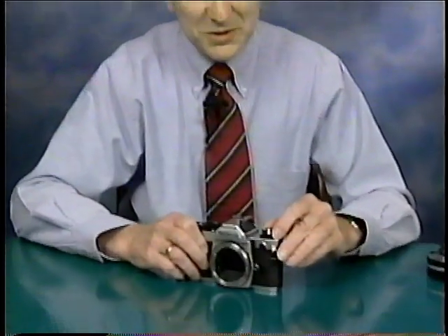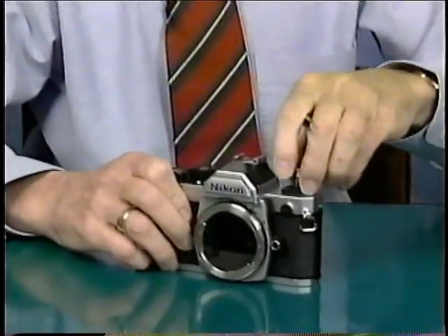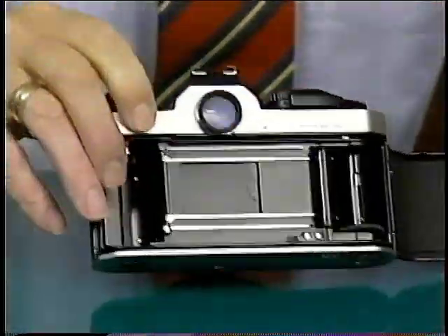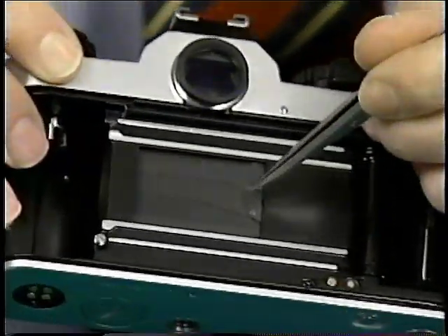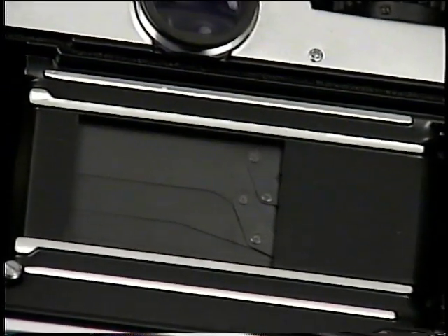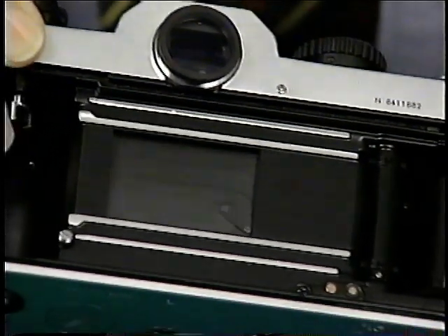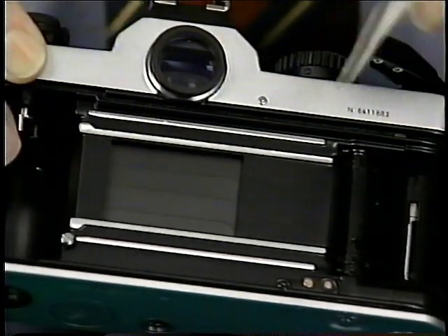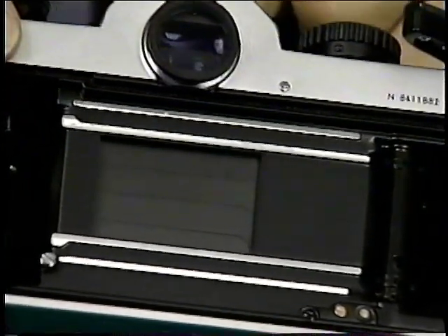Getting back to the camera body, let's have a look at the shutter system on a single lens reflex camera. Normally those shutters are located right at the film plane, and in this case it's a set of blades which travel in the vertical direction. If I cock the camera, you'll see, if you watch, the shutter moving. Notice that as the camera is cocked and the film is moved, one shutter blade always remains closed so that the film does not get exposed.